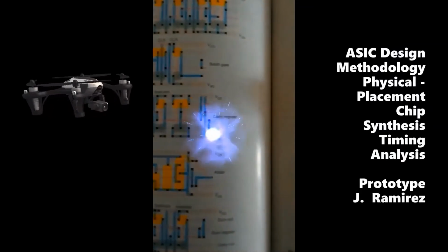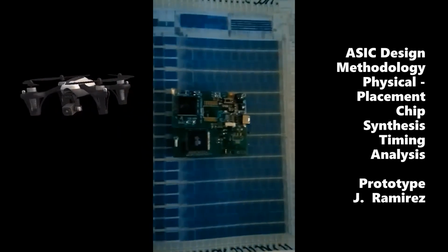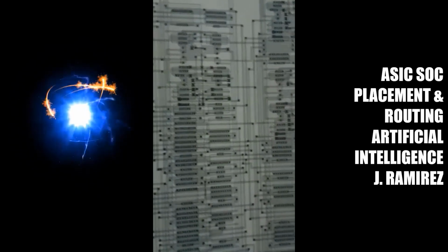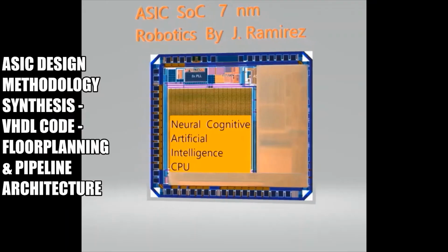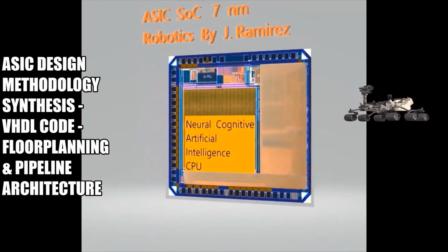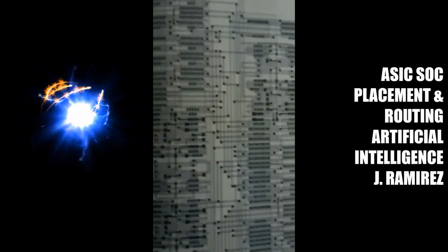Chrysalis Design Verifier is a formal verification tool that I used in order to logically compare different versions of the ASIC gate level netlist. I used this tool to verify that the different versions of the netlist did not change functionally during the design process, such as test insertion, placement, and route. This allowed me to proceed without having to resimulate at each step.